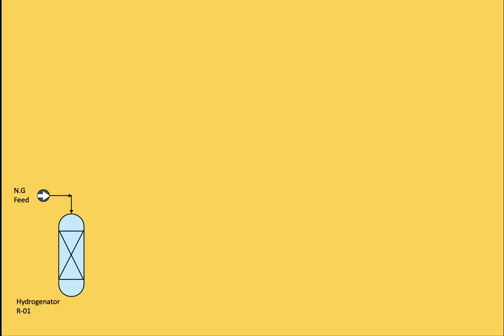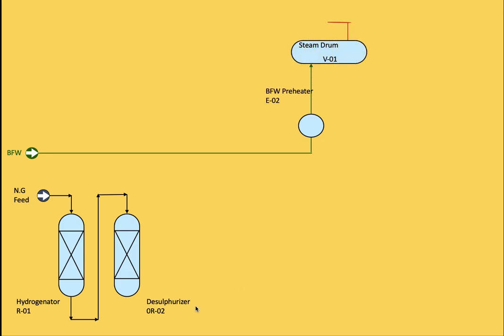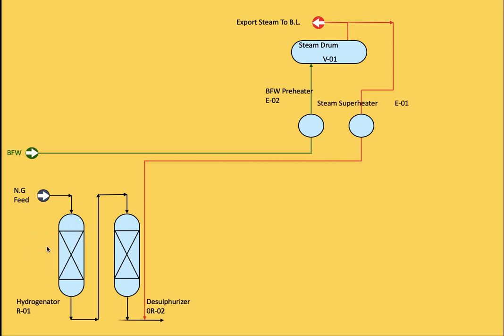When we discuss this diagram, it's clear that the first stage of the hydrogen production plant is desulfurization of the natural gas feed, or feed gas, to the unit. This happens in two reactors, R1 and R2 here. The first one is the CoMo catalyst reactor.